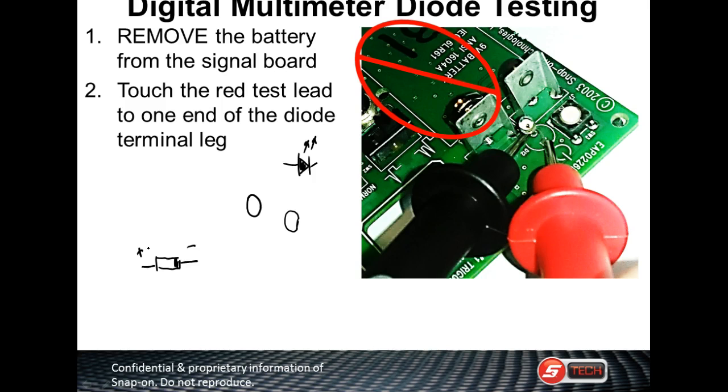So we can check transistors, and we can check some SCRs. These are silicon controlled rectifiers, which is what this is right here. I've seen diodes this big that go in a water-cooled jacket, and you have to compress them for them to work. If this was a regular diode, you can check it without water. You can check it with your meter.